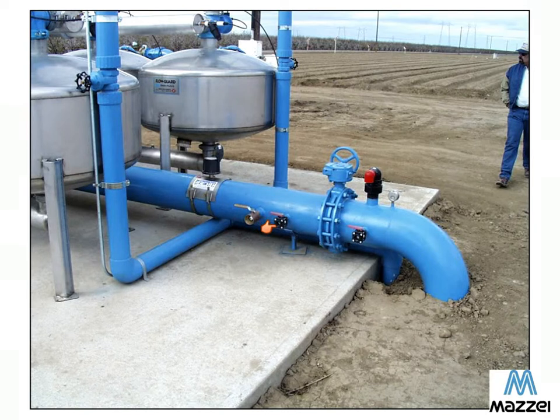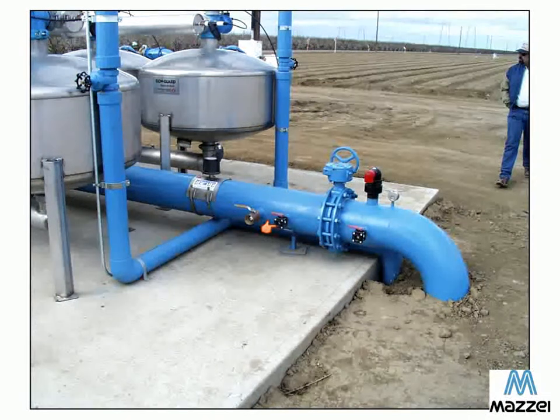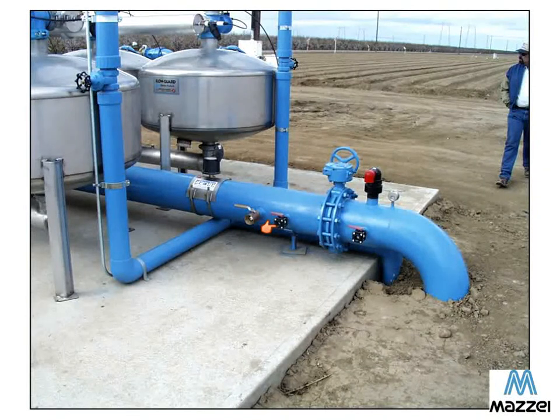And that's something, again, that we take into account in our injector selector tool. In a pressure reducing method, the tool will choose the largest injector that satisfies the need in order to minimize the pressure loss across your pressure reducing valve.